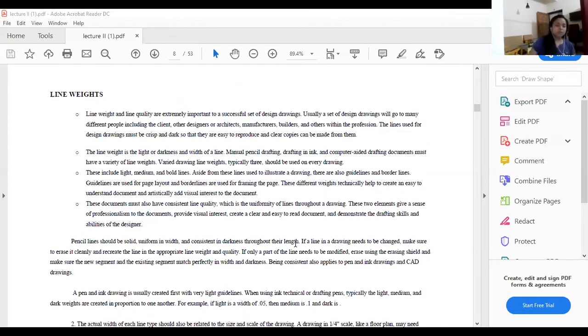Now, talking about line weights, you must have known about this whenever a plan has been made. Suppose Cheyenne has formed a plan. So in that plan, if the wall thickness and at the same time the cabinets, the interior details, be of the same weight, then it might create some kind of confusion in the site that will be executed, because the line weight determines and has a very important weightage in any kind of professional and technical drawing.